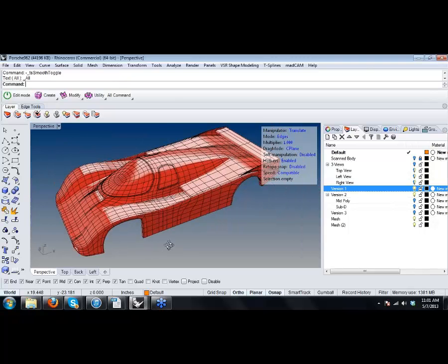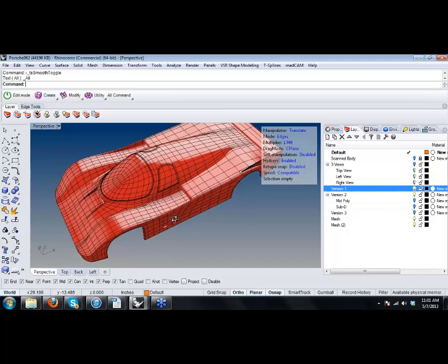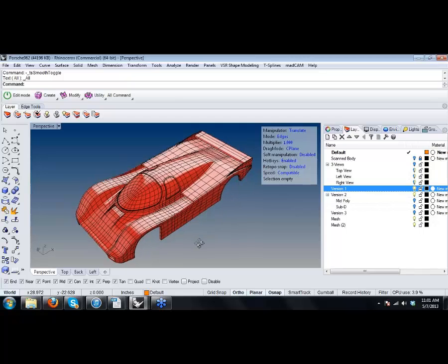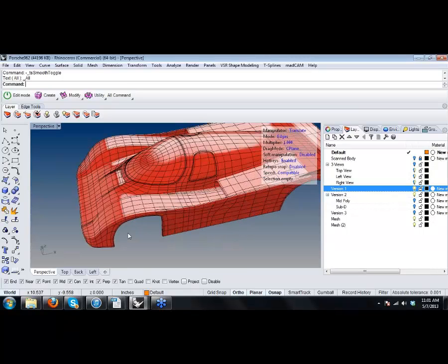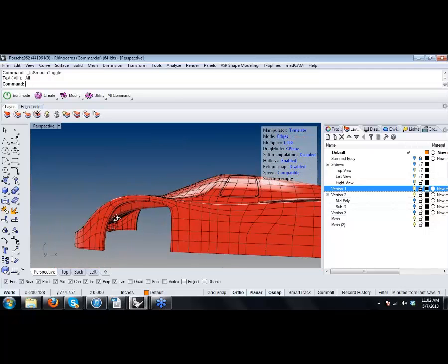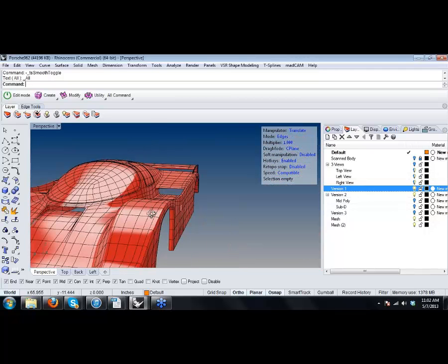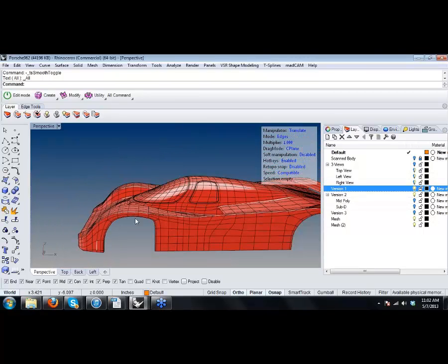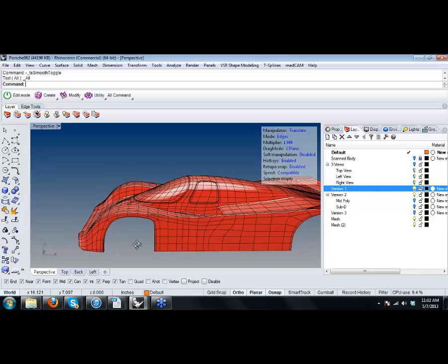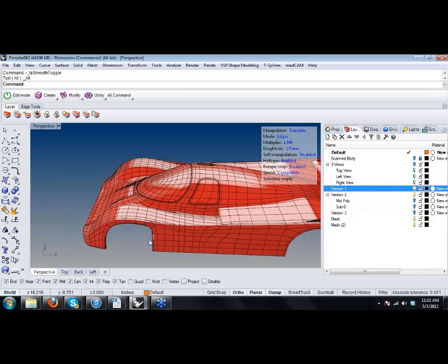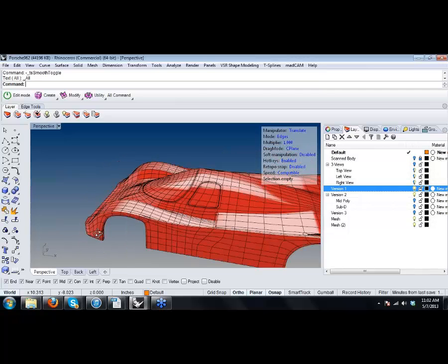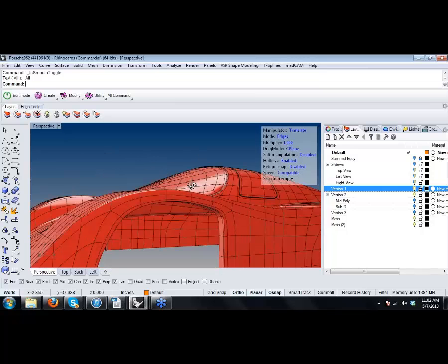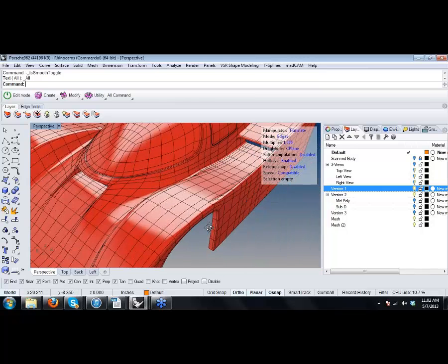I can definitely expound on that. There are certain parts of this that are appropriate uses of T-Splines, and certain parts that are just silly, right? In this particular case, the sides of these cars are really flat. So, do we really need to cut in the wheel arches here with T-Splines? No. We could have left this as a T-Spline totally closed off, come in with NURBS and just trim the hole in it, and then just blended this return in here. This shape is so simple, there's no point to that.